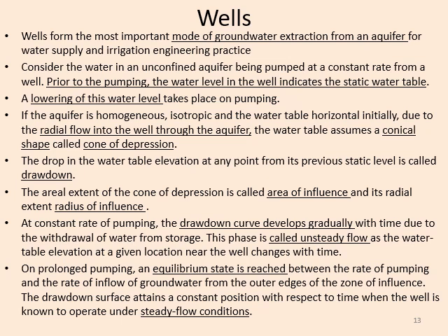This phase is known as unsteady flow, as the water table will gradually lower at a given location near the well, and it will change with time. On prolonged pumping, means for a longer time, an equilibrium state is reached